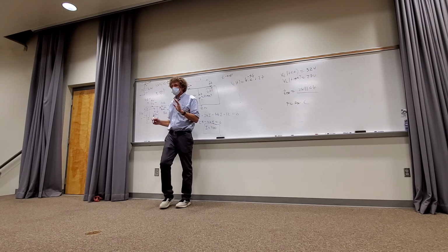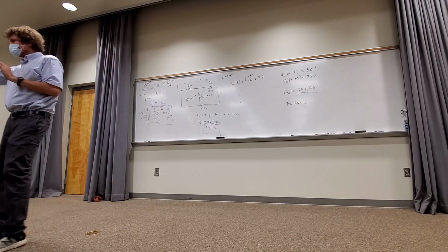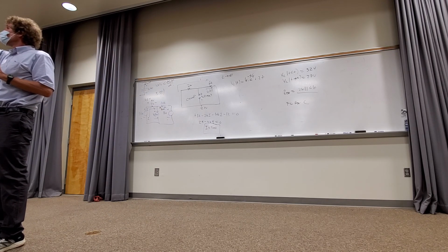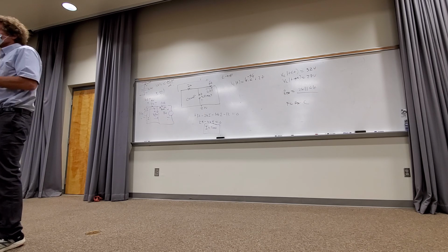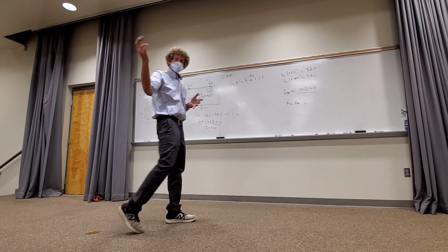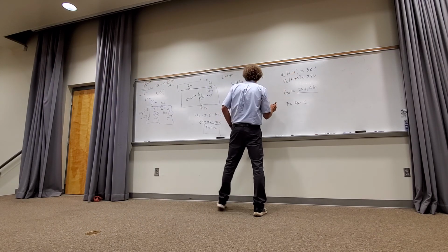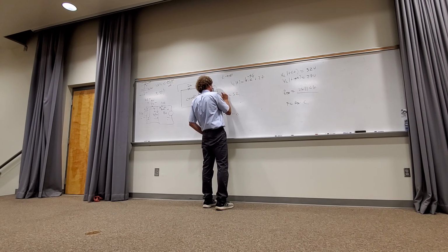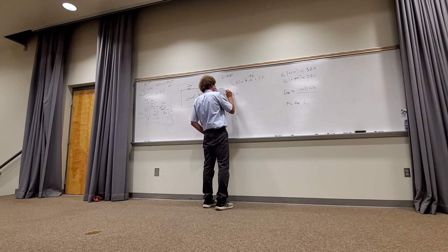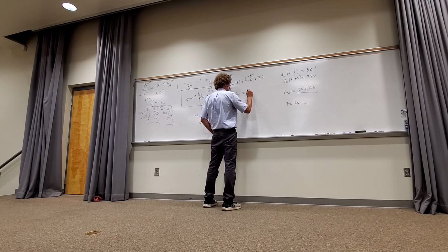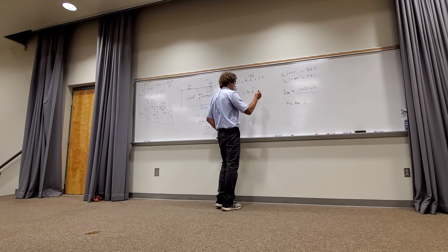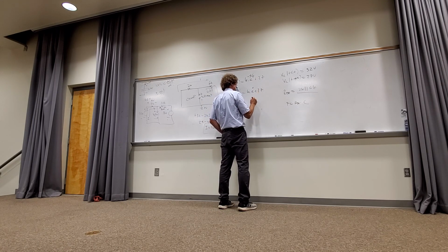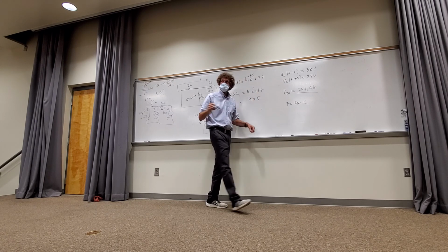How do I get K1? Any takers? Say again? I'm sorry? Plug in K2 and then when t is equal to 0. Exactly. Did you hear her? Evaluate that equation at t equals 0 and set it equal to the voltage across the capacitor at t less than 0, because they can't change instantaneously. So you set it equal to 32. So then you would have 32 would be VC for t equal to 0 positive. 32 is equal to K1 e to the 0, which is 1, plus 27, right? Or K1 is equal to 5, isn't it, class?